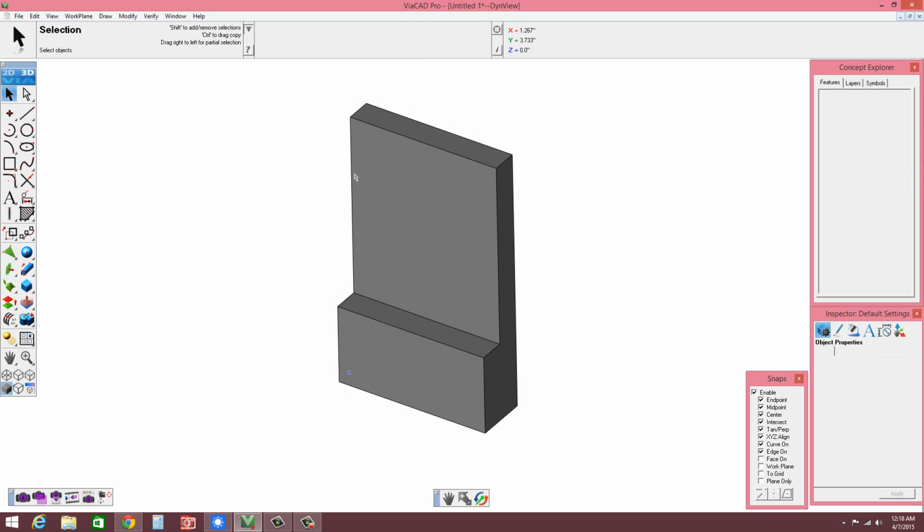do different things that you want. Now the next thing I'm going to do here is I'm going to go to the circle tools, and there's several different types of circles to choose from. You can circle one point, or in this case circle point center. I'm going to go to a center point circle, sorry. I'm going to go ahead and select that one. And then roughly around here, we actually want it to be approximately, the Y needs to be, and right over here is where I'm looking, X, Y, and Z. I'm just going to kind of align myself in this upper left corner here and click and drag out a circle.